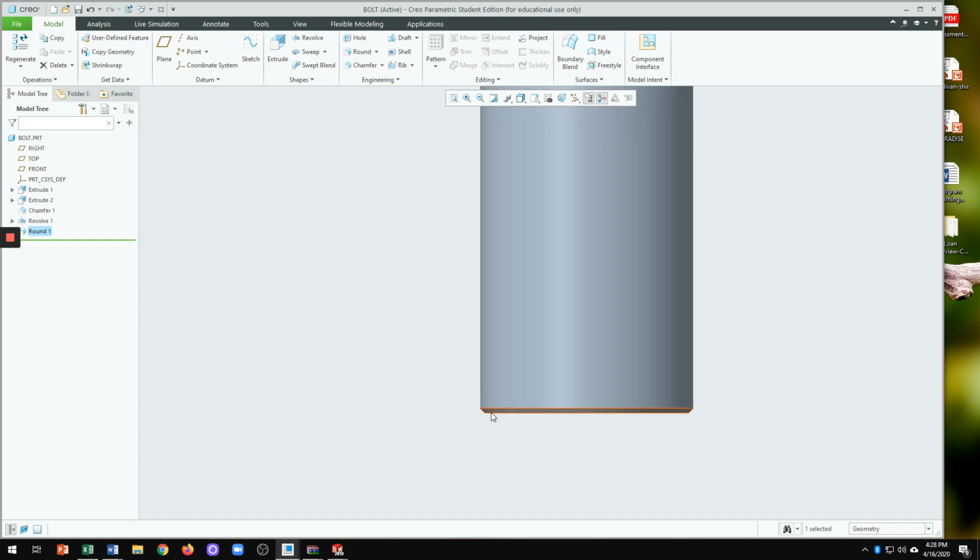All right, so now just watch very carefully. I'm going to create a threaded shaft. This is a V-shape American National thread, 60-degree angle, and then I'm going to use the information provided, but I'm going to modify it a little bit because I wanted to have the pitch a little bit smaller than 5, because there is a range, between certain nominal sizes of the shaft, from 40 to 50, for example.